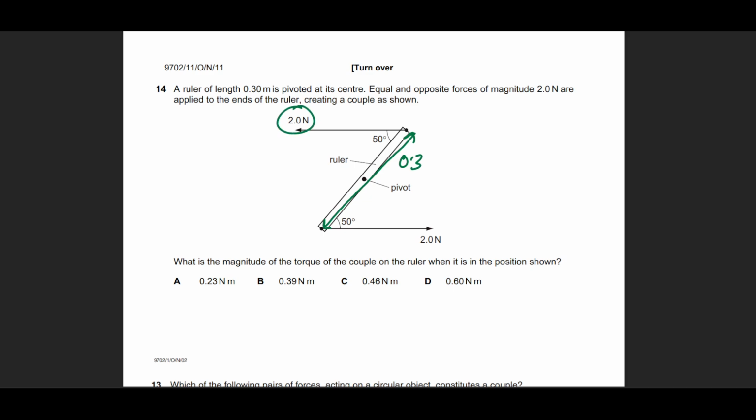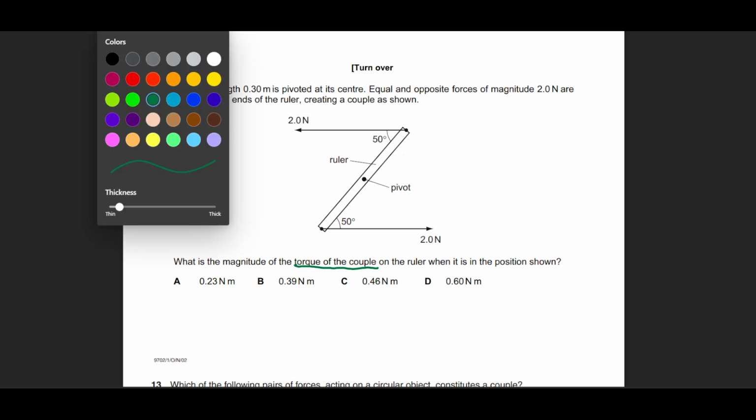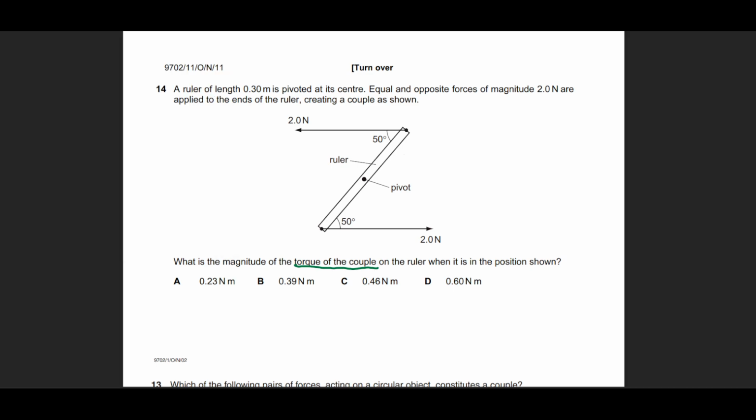Equal forces are being exerted, right? They are anti-parallel. One is towards the left, one is towards the right. So yes, this will be creating torque of the couple. But how do you solve this? You see, we discussed that there should be a perpendicular distance between them, right? So we can solve it in two ways over here. What students generally do is memorize the formula of this situation, but we're not going to do that. We need forces with a 90-degree angle.